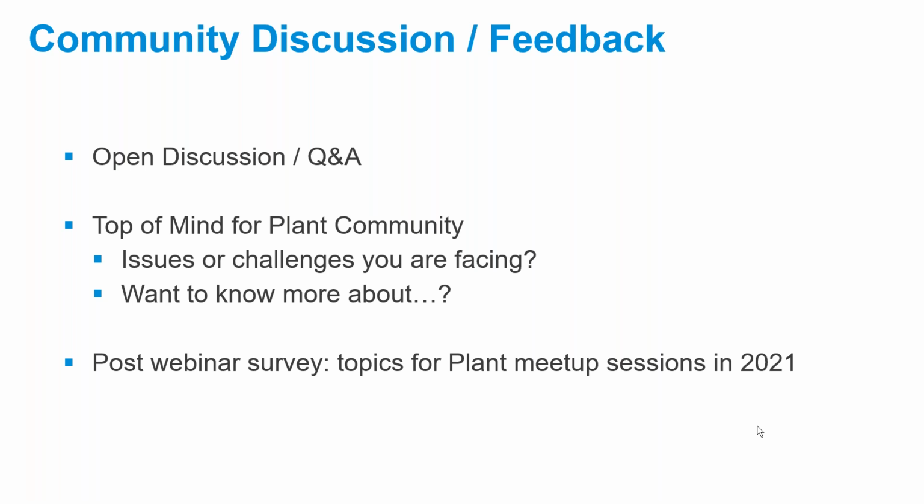Yeah, he says it's basically compared to other software out there that he's used, it takes more steps to insert components with Plant 3D. As I say, basically you're dragging from a tool palette onto the pipe if you're placing a component onto piping. If you're putting it in space, then of course you need to know where it's going to go. I usually have a routing line or something like that.